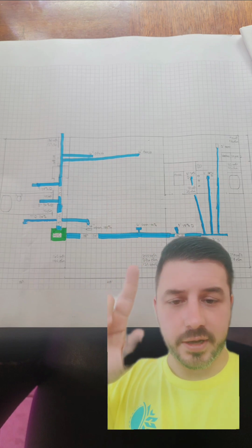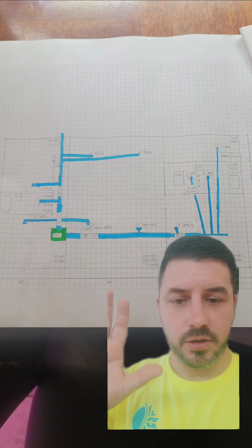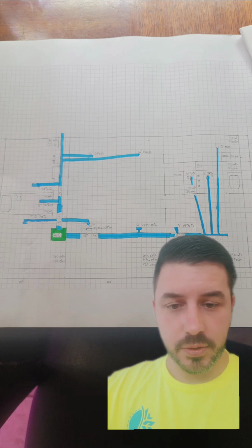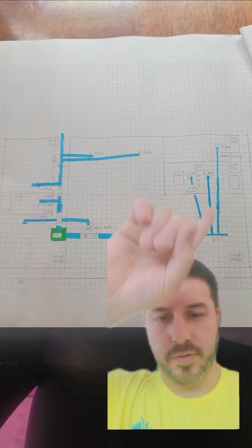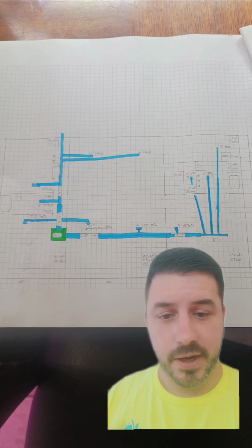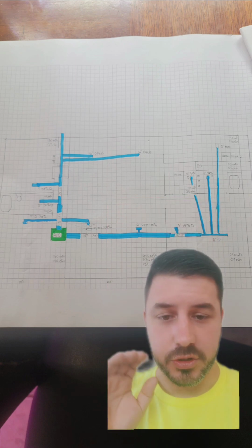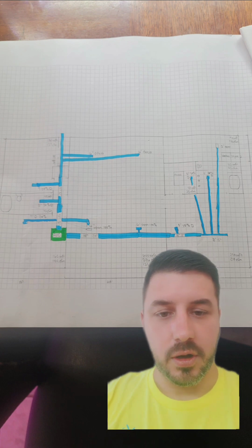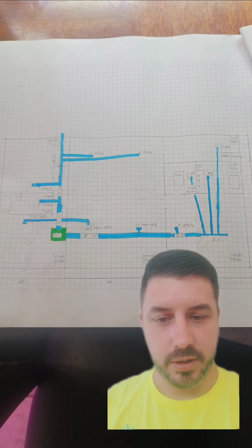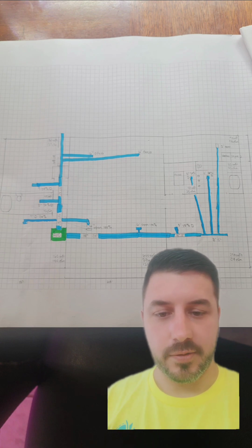You don't need to worry about the size of it just yet, all the ducts and everything. You're just looking for the longest run from the air conditioner and the return, including the return. Let's say over here in this top right corner, we extend the furthest away. We got to find the total effective length. If we were to straighten that whole run out, the turns, the bends, all that stuff, we would have to account for the turn because we lose pressure in it, right? We call that total effective length.